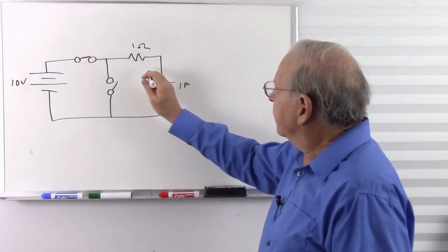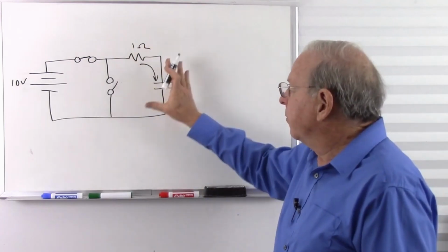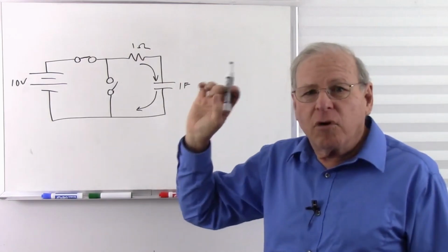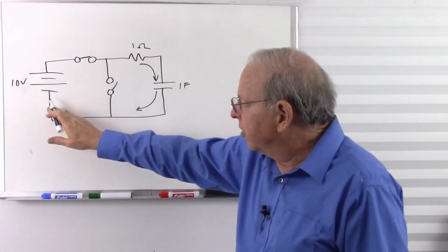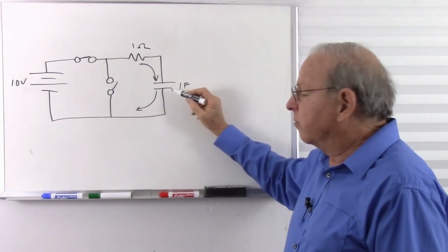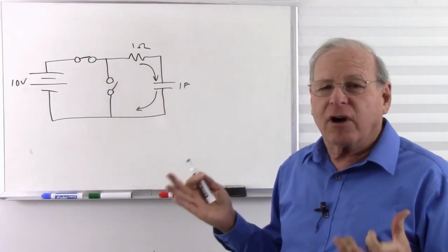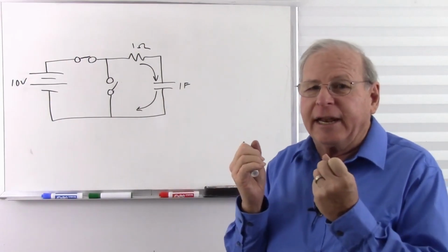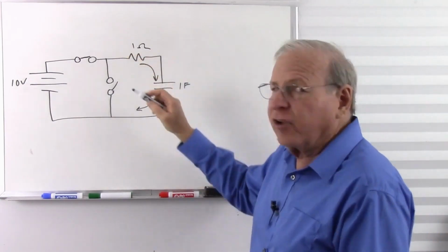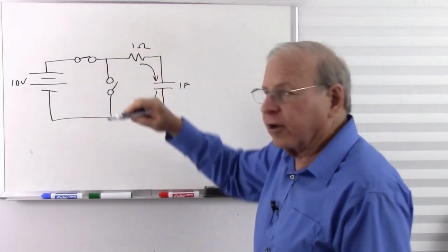So what we have is energy flowing into this side of the capacitor, and so electricity is flowing there and piling up, and that is pushing electricity off the other side. Now, of course, what is happening is we have electrons flowing from the negative side of the battery, and they're piling up on this side of the capacitor, which of course is 2 plates of metal separated by an insulator. The electrons can't cross that insulation, but they can influence electrons on the other side and push on them, and it pushes electrons off. So every electron that piles up here pushes off another electron on the other side.